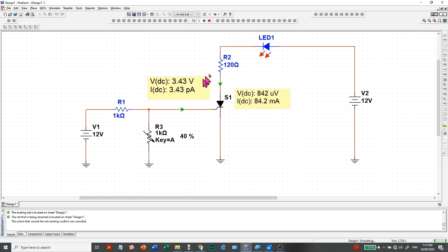Okay, so we are turned on because we have triggered it once, and because the current is more than the holding current, it maintained the on state. So there's no way we could turn it off if we just use our gate trigger voltage. So in this case, we could use two methods of turning off the output part of our circuit.